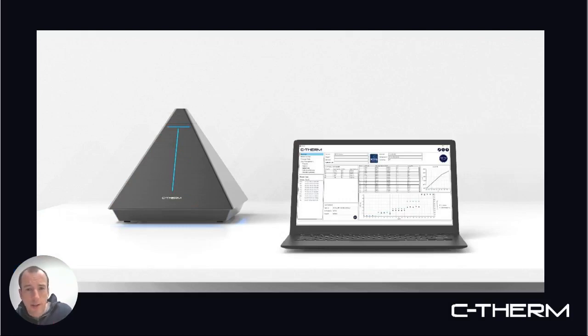The software provides, it's hard to make it out on this slide, but it provides a really nice graphical and tabular format. So one of these columns is conductivity. You don't have to do any regression analysis with the MTPS method. It is basically point and click in terms of generating conductivity. You press start, it's going to start generating conductivity data for whatever's in contact with the sensor. So it is by far the easiest way to measure conductivity of the available methods, both in terms of what's available on Trident and more broadly speaking.